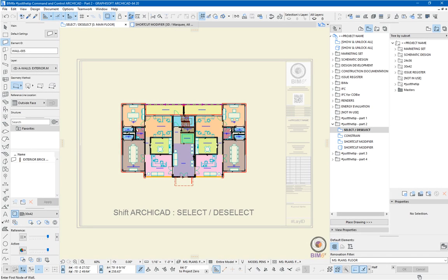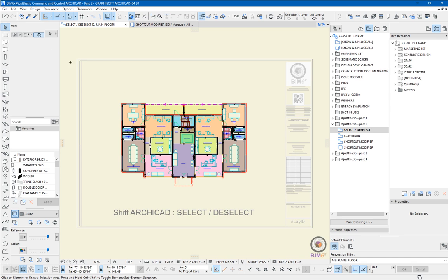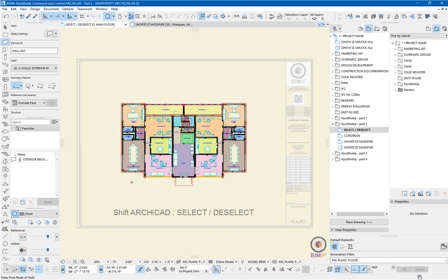Specifically in this case, we're looking at the Shift key and 3 main functions it performs. So the first one is the selection and deselection tool, and this is one of my pet hates really, to be honest. If I'm in the middle of drawing something, one of the things I hate to see is when somebody does this, realises they need to use a different tool, so maybe they cancel, press the escape key, move the mouse up here to the arrow tool to then go and maybe select this table and chairs, do something with it, finish that, and then go back to the tool that we were on before. There's a number of different ways to do that to speed things up, but the first thing is just don't go for the arrow tool in the first place.